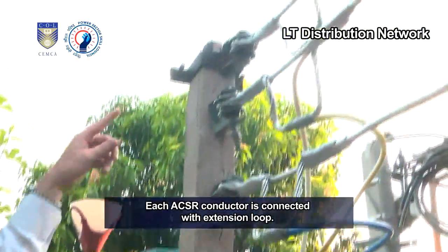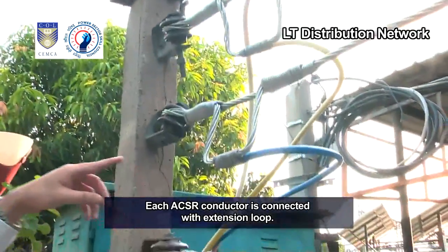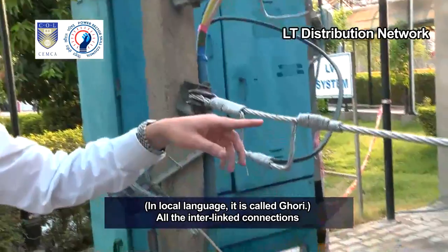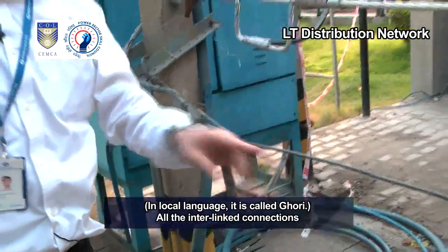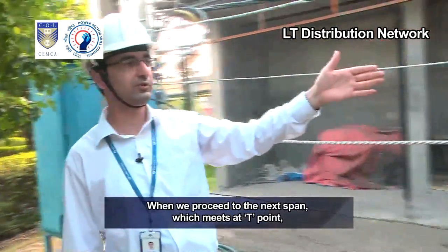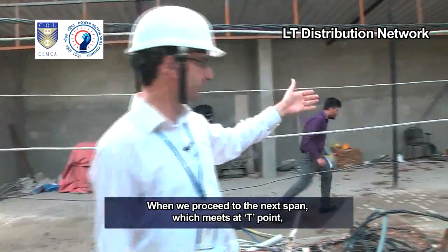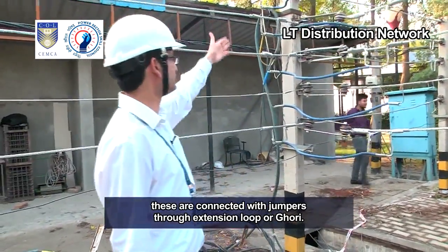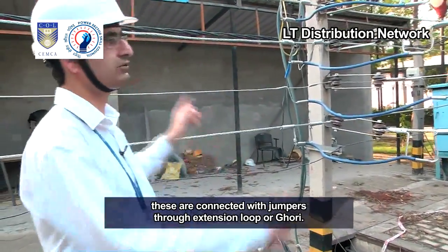Each ACSR conductor is connected with extension loop. In local language, it is called ghodi. All the interlinked connections to the lines are made from these extension loops. When we proceed to the next span, which meets at T point, these are connected with jumpers through extension loop or ghori.